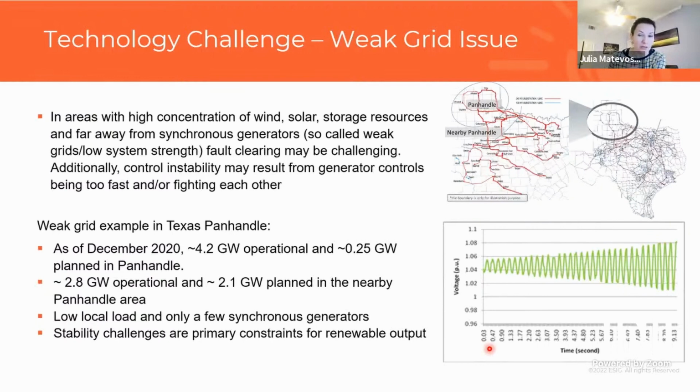And so as power started increasing at that plant, they saw these voltage oscillations without any disturbance on the grid. This was just from extra injection into the point of interconnection from a resource. So they saw this first time, and they were able to replicate it in studies. These issues are studied during interconnection, and also every quarter ERCOT runs what they call a quarterly stability assessment.